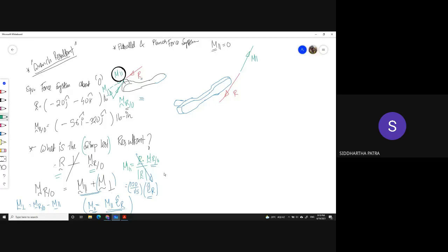And this diagram may look confusing to you because I'm drawing it outside of the geometry. How can a force and a moment act outside of a geometry? It's only for mathematical representation. If this bugs you, then in your mind, imagine there is some sort of rigid connection to this very point with this body here.